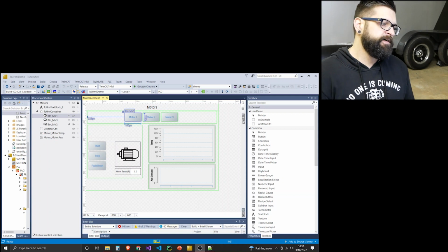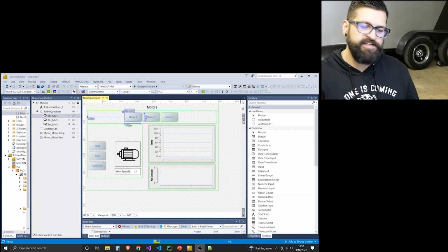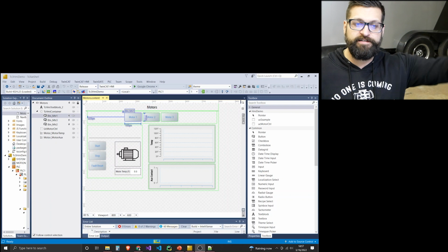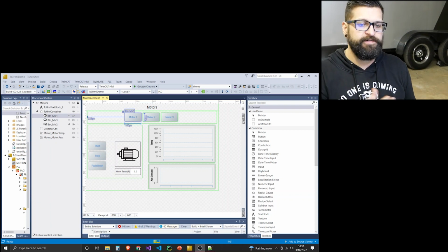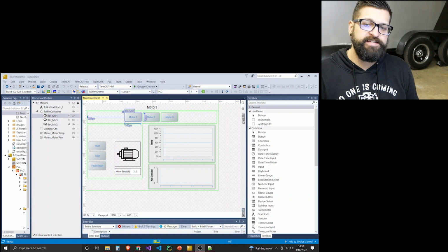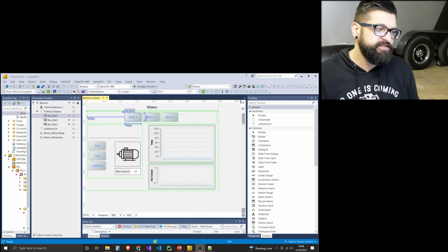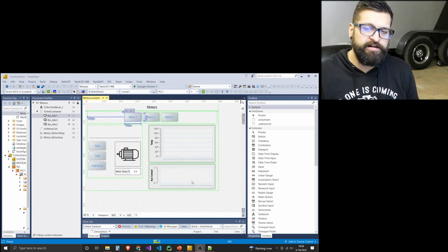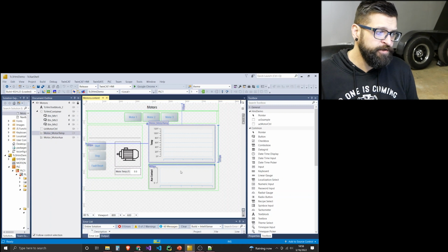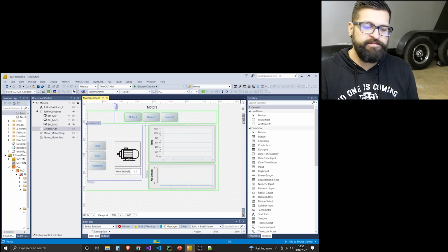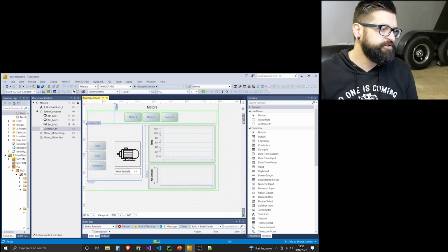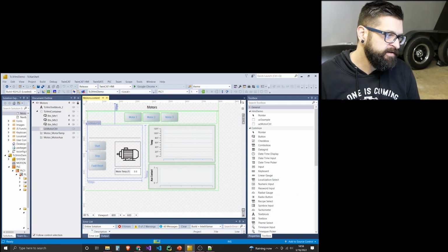Okay, so the most complex part of this HMI is the motors page. So we're going to focus on the motor content file to see how I've dynamically passed around the 3 different data sets for each of my motors, and got them all to display in one temperature chart, one aux contact chart, and one user control for my start, stop, fault reset, and changing the colors of my motor image to show the operator what the state is.